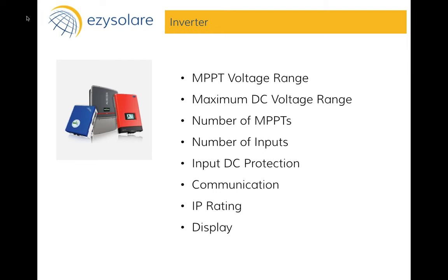But basically, what this degradation refers to is that all of these panels, the rated power that you get, whether that be 250 or 300 watts, etc., is going to be at a particular temperature, which is 25 degrees Celsius, when there is enough sunlight available. But what happens is that when you keep on growing the temperature above 25 degrees Celsius, which is very common in Indian conditions, the panel output starts to decrease.